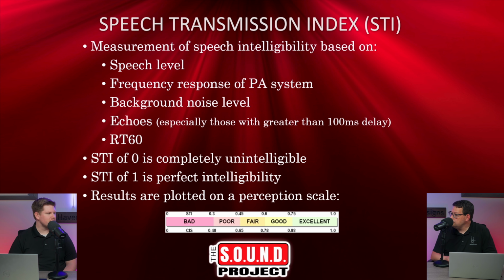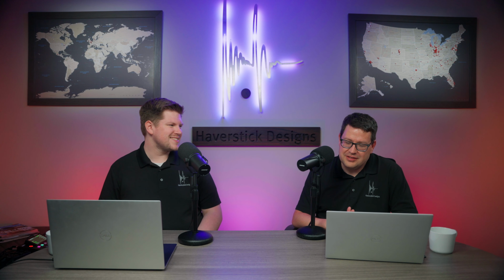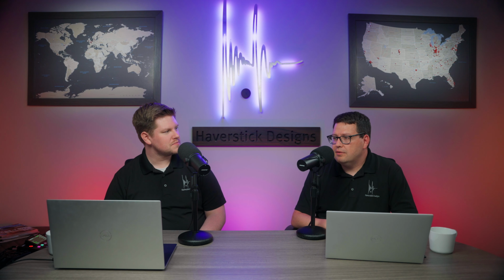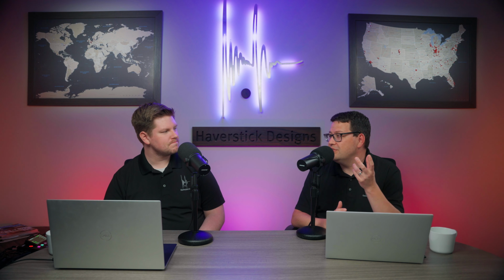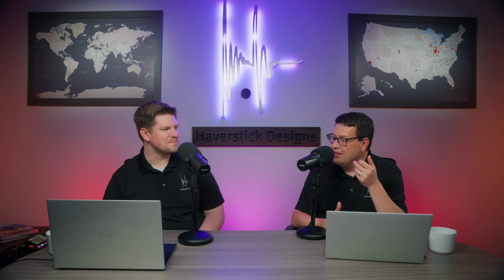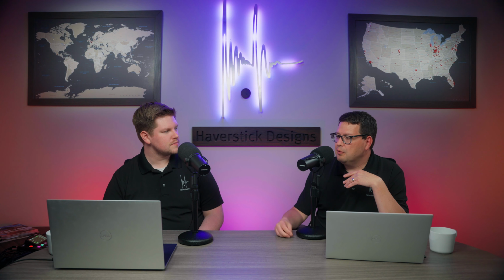With the STI, that's obviously very objective, but especially in churches, we also sometimes do subjective listening tests. That's something I'm doing tomorrow, actually. We're going to test a church tomorrow in Ohio, and there's a list of standardized words. They're all one-syllable words, pretty easy to understand, unless you're in a bad acoustical environment. I give audience members a multiple choice sheet where they circle which word they think I say through the sound system. Typically we do 50 words, and we do that test 3 different times.